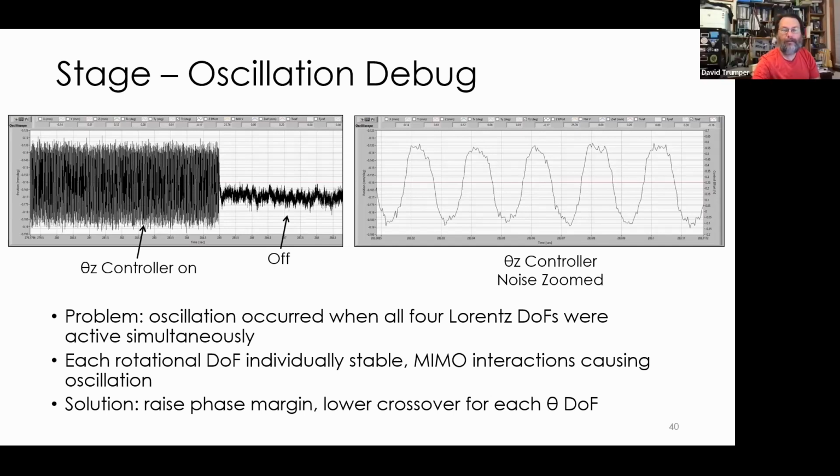As a comment, this MIMO decoupling works pretty well, but there's no firm guarantees about stability because you never get the decoupling working perfect. So driving one axis drives the others, and that then gets into the other loops, and you can easily get instability from these residual interactions. The nice thing is SISO controllers with roughly decoupled loops are pretty easy to debug.